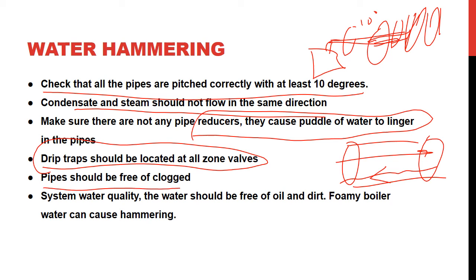Pipe should be free of clogs. No clogs are allowed in a steam system. Water quality is very important. It should be free of oil or dirt. If you have oil, then you have foam.